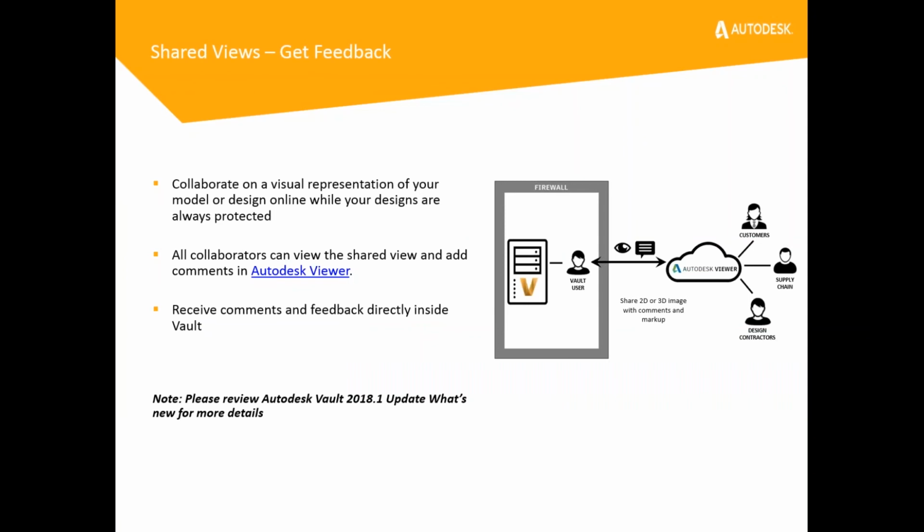I already mentioned that the Autodesk viewer is the online tool that is cloud-based, but we can send our views out there. It's got a kind of ticker on it almost, where those views will expire after so many days. So that's the nice thing too. It's not just out there forever. It uses the visualization file for Vault, so you're not sending out your IPT or IAMs, your actual design data. It's a lighter view, so it's harder for somebody to potentially steal that data, or if you send it to a supplier, they can't just copy it and send it off to some of the other people they're working with. So you can trust that it's fairly locked down.